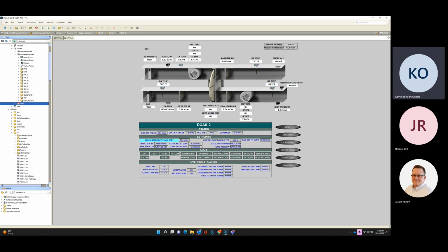So let me regurgitate that back to you and see if I'm anywhere close to what you just said. Okay. So really, we're not as concerned about duct static as we are meeting flow. And we're using duct static to meet flow, but the flow is constantly changing based off of what the boxes report back they want. Right. And then you're trying to maintain what they need or what they're asking for using duct static pressure as a driver. Is that fair?